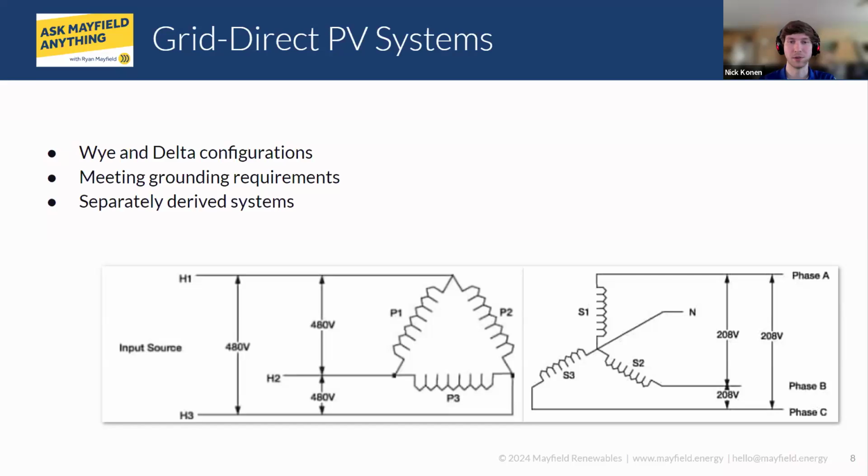Yeah, absolutely. Again, the most common setup we'll see is the Delta facing the utility side with the Y side on the inverter side. In battery storage, it's flip-flopped a little bit, where often the BESS wants to be an ungrounded system. So typically it's a Delta facing the BESS side. And with the absence of the grid, being powered only by the BESS, it's good to have that Y neutral on the grid facing side to provide those single phase loads.